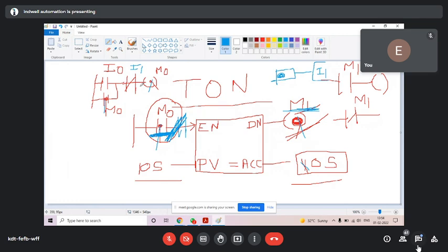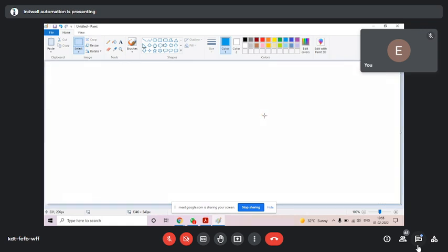Okay, now it is time to implement timers in a project. I told you timer is very important for your project, so I shall give you some examples. You have to make the program. I am sure you understood that if we have a push button, we have to latch it always, and you understood the function of the on delay timer also.